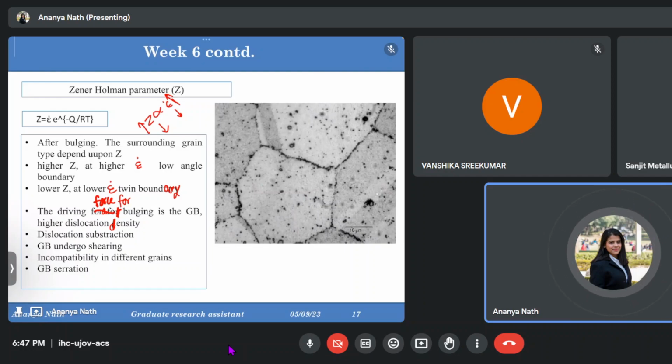because no extracurricular things are happening inside the grain boundaries. The dislocations were normally moving and getting arranged at a low energy configuration. Only that thing is only happening at the time of deformation. So the driving force for this is also like the bulging in the grain boundary, then migration, orientation, those things.